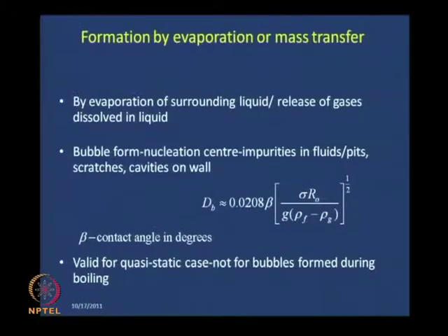So, under such circumstances what do we have? We find that in this particular case the expression is in terms of equivalent diameter. The equivalent diameter which is just large enough to break away from a horizontal surface is obtained from the expression here, where, since the surface is important, beta, the contact angle in degrees, also becomes important and is included in the expression.